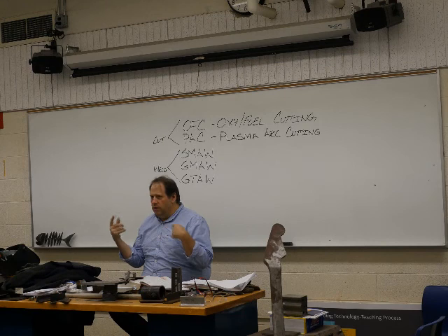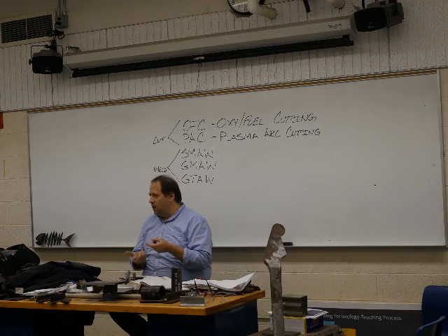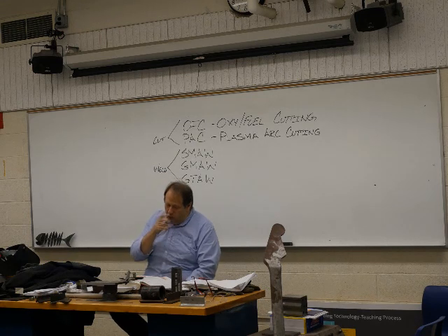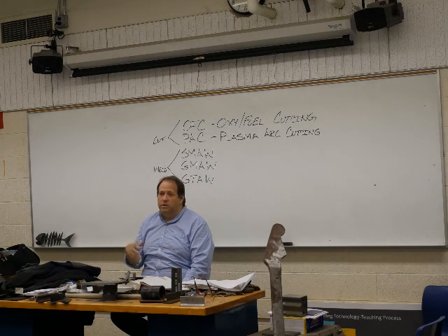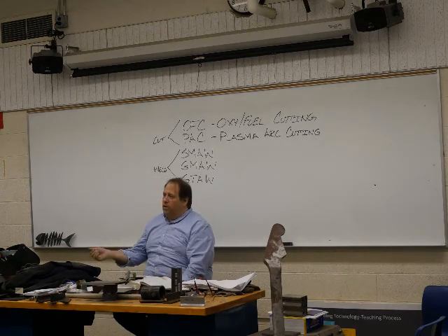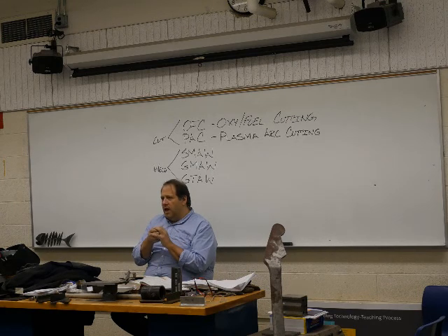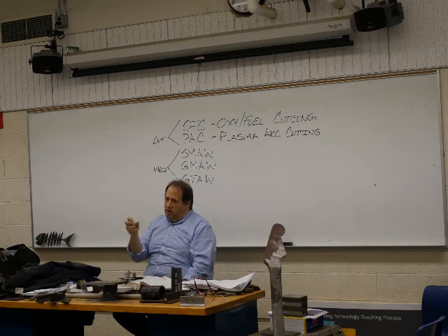Gases in general, you don't think about gases actually being able to conduct electricity. But in this process it does. But because it's so different, because it is ionized, it's a different form of matter. So what we're doing is introducing an electrical arc into a gas. And in our case, all we're using is shop air, nothing special, just a compressor. We throw electricity into that gas and we ionize it, and it really kind of supercharges the gas. And then we take that gas and the arc and we make it go through a little tiny orifice.